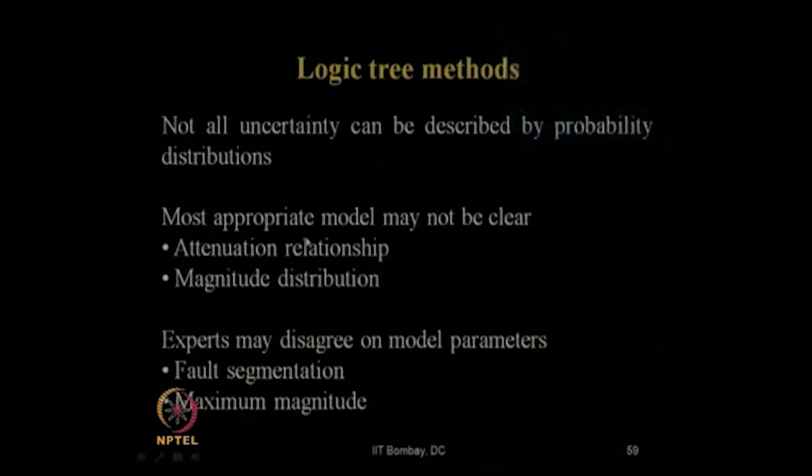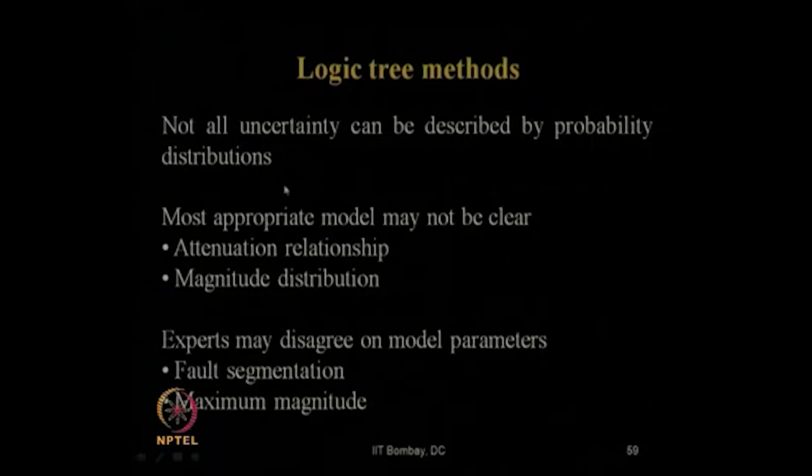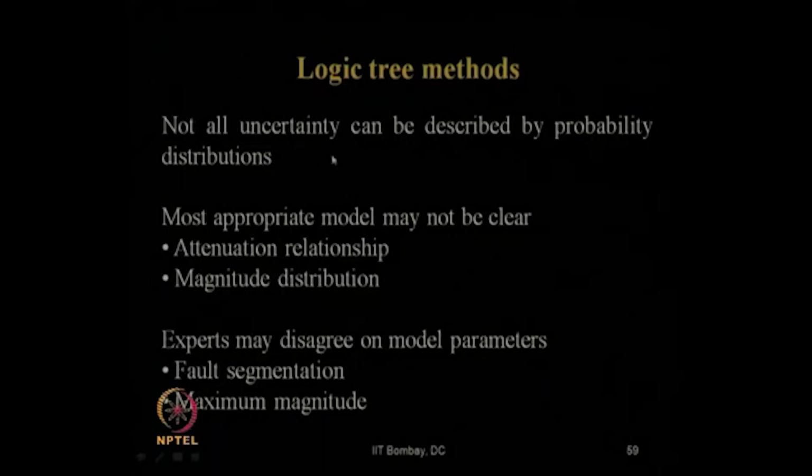Now, let us come to another important subtopic, which is known as logic tree methods. What are logic tree methods? Now, we have talked about various uncertainties, majorly 4 uncertainties involved while computing probabilistic seismic hazard analysis. Now, all these uncertainties are not equally important. Am I right? There can be different importance of different uncertainties involved in the process.